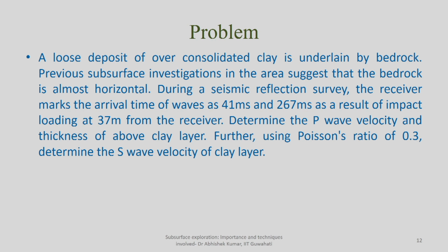Previous subsurface investigation in the area suggests that the bedrock is almost horizontal. Almost horizontal means you have to take up the first example where the bedrock was almost horizontal, and then you determine the thickness as well as the shear velocity and primary wave velocity of the medium.